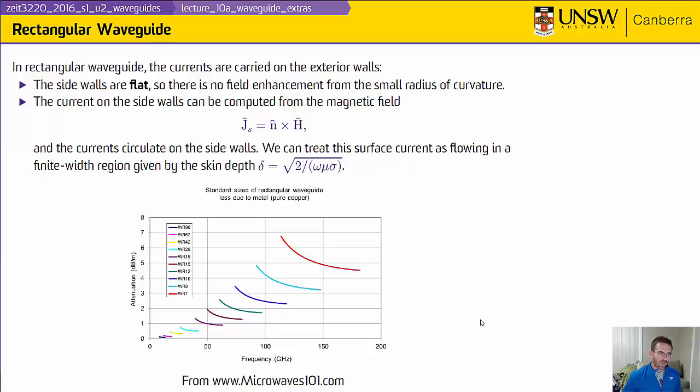So at lower frequencies, we know we can deal with the losses associated with the conductors, and we can use coaxial cables. When we start getting up into the gigahertz frequency range, there's a trade-off between the advantages provided by a coaxial cable and the disadvantages provided by its loss. And so in the gigahertz range, we'll often use either coax or waveguide, and that really depends on the power levels. When we have fairly high power levels, it's generally preferable to use waveguide, whereas at lower powers we can get away with using coax, and that's because at higher powers, if I have more loss, I have more heat dissipation, and that heat dissipation will cause me other problems beyond electromagnetic problems.